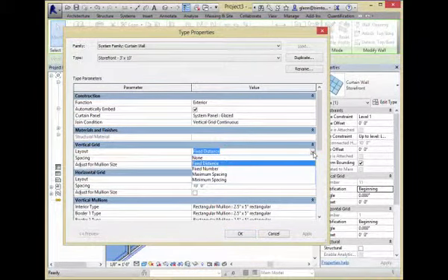There's some choices in here, and again, you can determine things about the pattern. Do you want them to be a fixed distance, as when you say 3 feet, they are going to be 3 feet? Do you want a fixed number, as in no matter how big the wall is, I want 10 panels in there? You grow or shrink the panels to put 10 panels in there. Minimum maximum spacing is the idea that if you do want to break it up, how big could they get? Maximum spacing 36 would say that if the panels turn out to be 30, 33 or 35, that's okay, but they can be up to 36. If it gets to be over 36, make another whole increment. So that gives you a little flexibility. But I'm going to do fixed distance right now because that's a pretty easy one to understand.